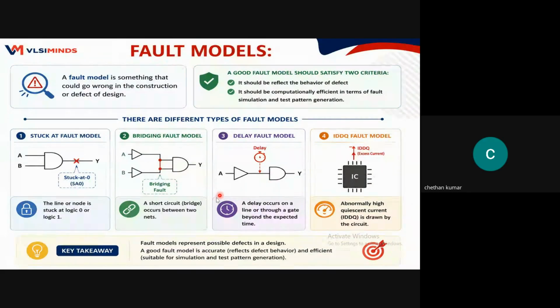Those patterns only will be delivered to the ATE to test with that particular timing constraints. Whatever constraints they give for generating the transition faults, they will give scan mode separately and functional mode separately. They will give different modes: one is functional mode, another is DFT mode. Again, in the DFT mode, for MBIST, based on the customer requirements, they will give different SDCs. For MBIST a separate SDC, for scan mode a separate one, and again slow capture separate and fast capture separate. Like that they will give the SDC files.